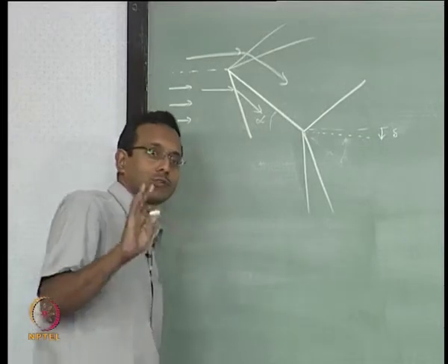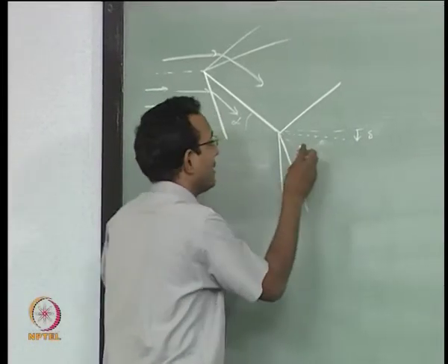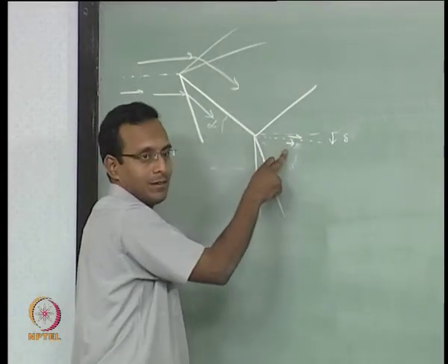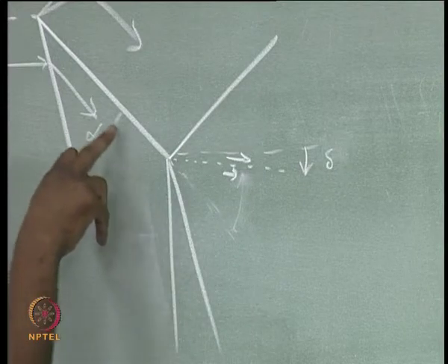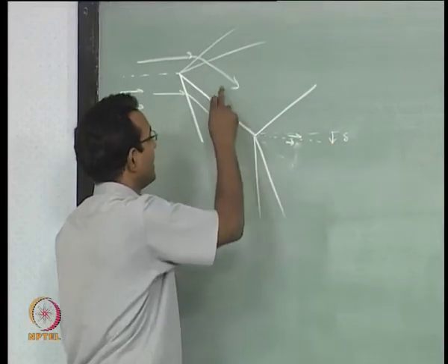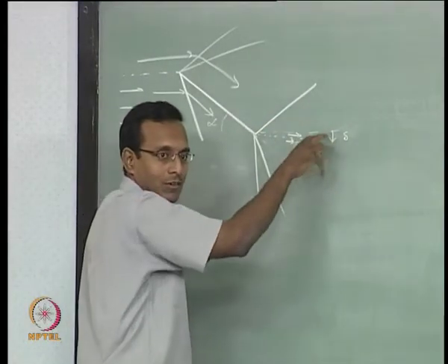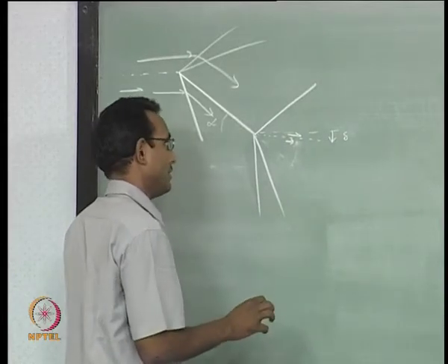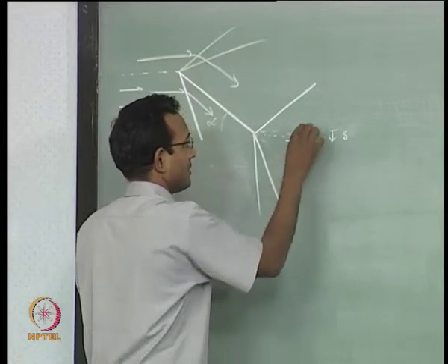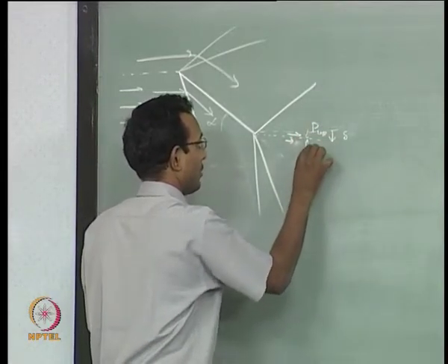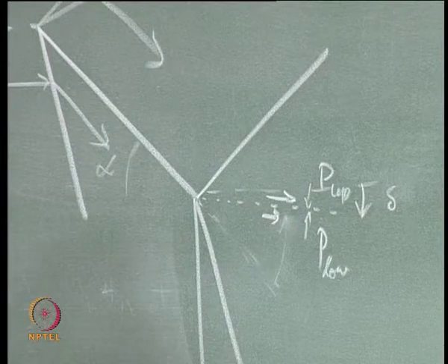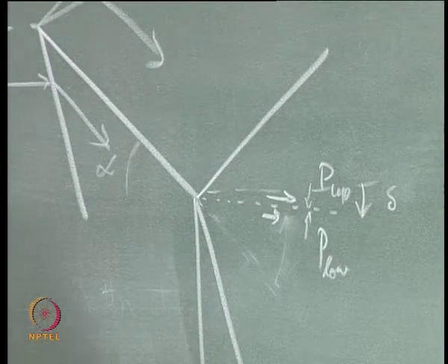Of course, we just told how to solve this, we never solved it really. I just told that across this region I am going to have velocity vector directions parallel, which means I should turn from this angle through this expansion to the same delta downward, and the same thing on the top. Oblique shock will make it turn only up to that point. That is what we said. That is not enough. We also have to tell that the pressures across the surface, P upper and P lower, must be exactly the same.